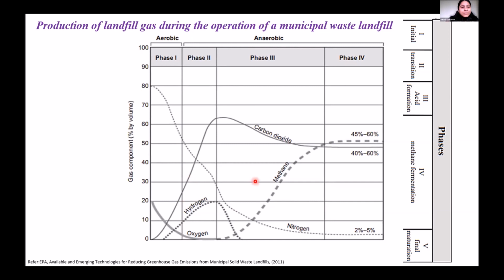So once the municipal solid waste gets deposited in the landfill, what happens there? The biocomponent of it has to get stabilized, and ultimately this results in the production of landfill gases. This entire process of stabilization happens in two stages. The initial portion is the aerobic stage, and the later one is the anaerobic biodegradation. The aerobic dominates in the prior part, and later the methane generation, which is mostly significant, happens in the anaerobic degradation of the waste.